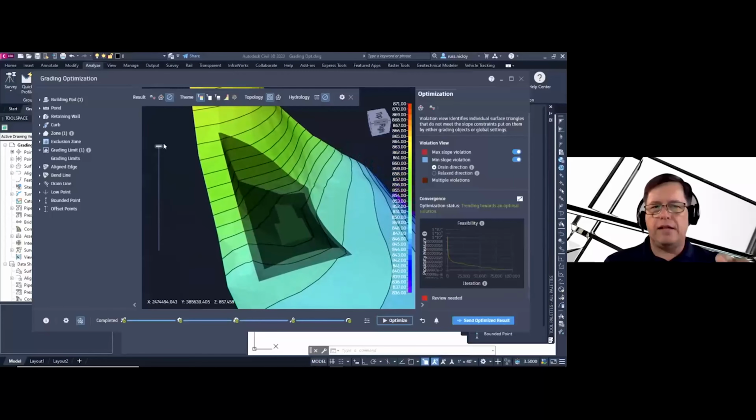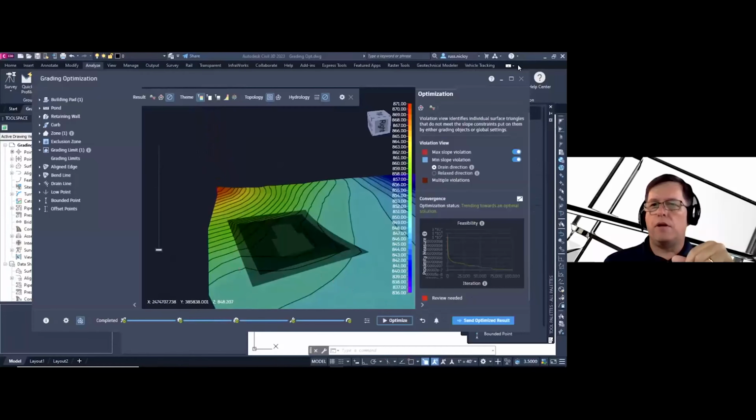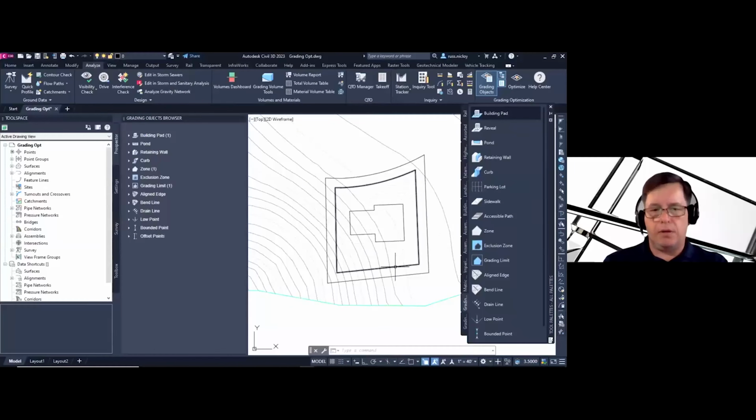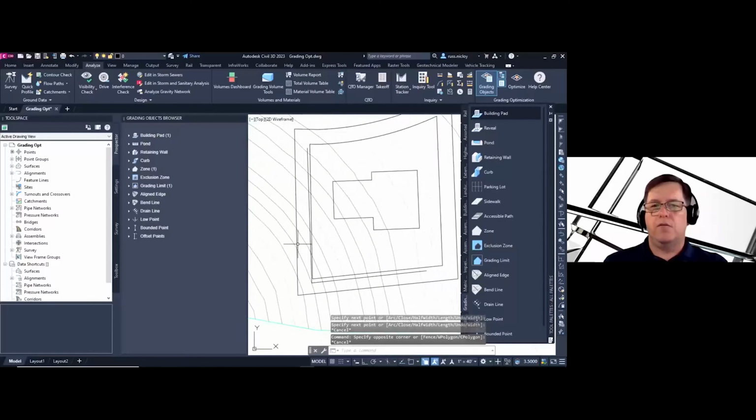And I think that to prevent any heavy slopes through this area, I'm going to put a retaining wall in there. So I'm going to close out this. I'm not going to accept the results, and I'll kind of back out. I'm just going to draw in a polyline roughly where I want to tie it in, up into the hill here. Yeah, make sure that that wasn't overstriking that.